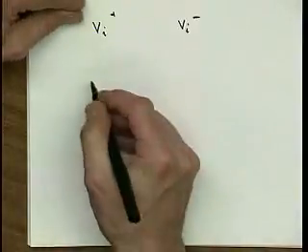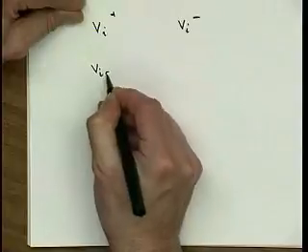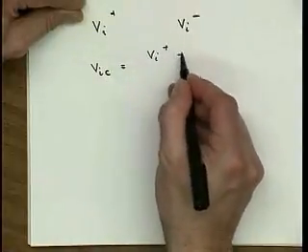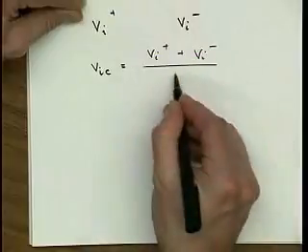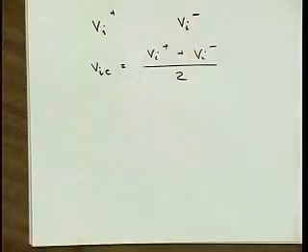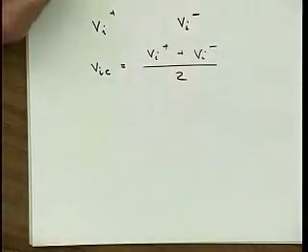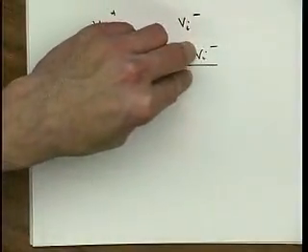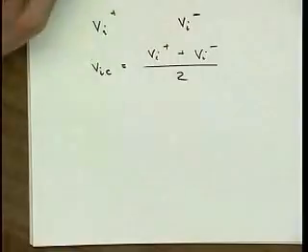What we also have is an input common mode voltage, VIC, that is equal to the mean of VI plus and VI minus. Okay? That's this common mode that, let's say, comes from that voltage spike because of the misbehaved inverters. And so sometimes we want to know about this just to be sure that it is suppressed appropriately.